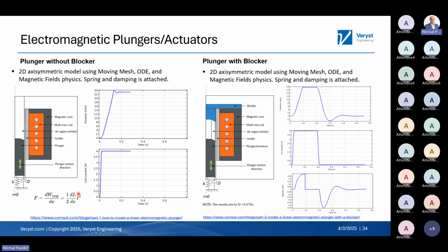So due to the reluctance, basically there is a reluctance force which is defined by the change in magnetics, or the magnetic gradient of the magnetic energy. In this case, this is allowed to move up without any fixed block or position. It can go all the way up, no physical blocking.